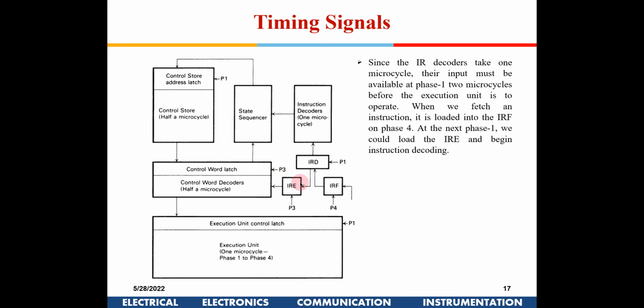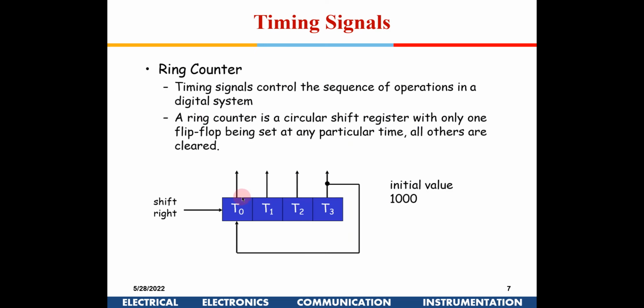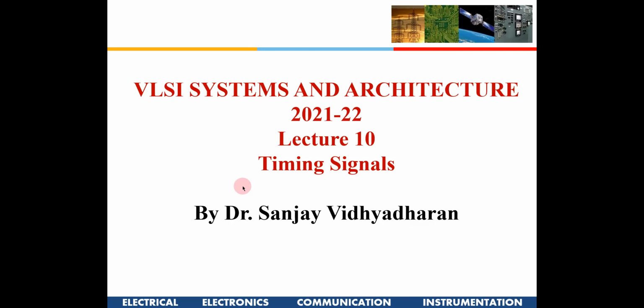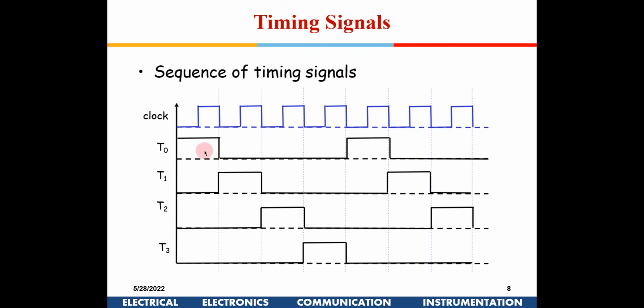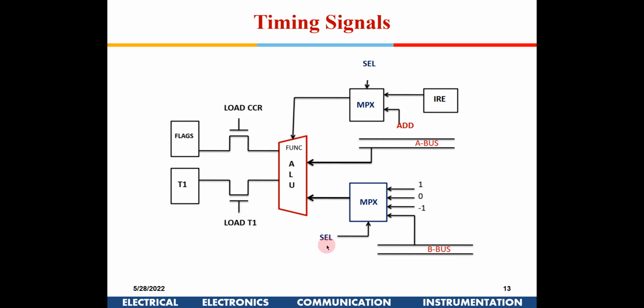If you don't use multiple phase clocks, instead of 1 clock cycle, you might require 4 clock cycles for the entire thing to complete. So using multiple clock signals of different phases like these ensures a staggered operation of the clock signal. Using these multiple signals ensures perfect timing, and gives time for each unit to complete its operation. So that is the reason we use multiple clocks in these.